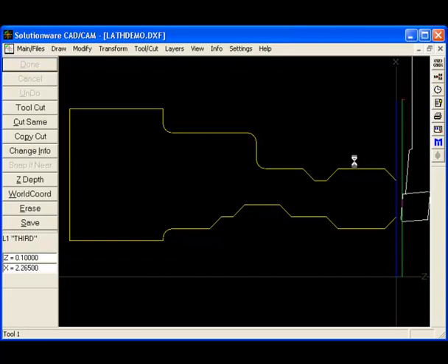You can use the number keys at the top of the keyboard to speed up or slow down the display. If you press number 1, for example, it'll slow the display down. If you press number 2, it'll speed it up slightly from its default speed. So if I press 3 or 4, it'll really pick up here. So we've got 2 or 3 roughing passes and a finish pass. Here's the finish pass here. And then it'll stop and wait for you to do the next thing.